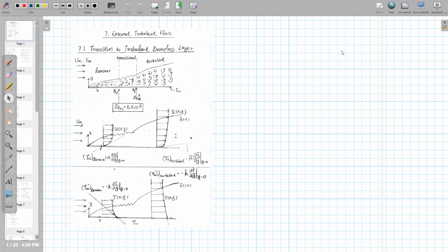In the last lecture, we started introducing some basic concepts for turbulence. We talked about how turbulence basically includes all the fluid quantities having a fluctuating part, compared to the mean part. And we have several ways to do the averaging. In this class, we only focus on the Reynolds averaging.